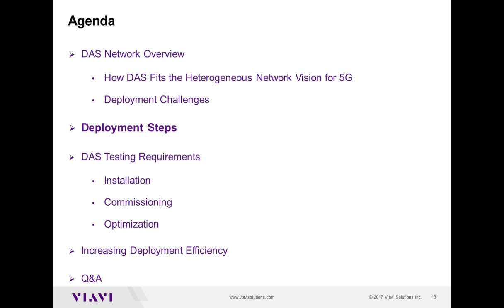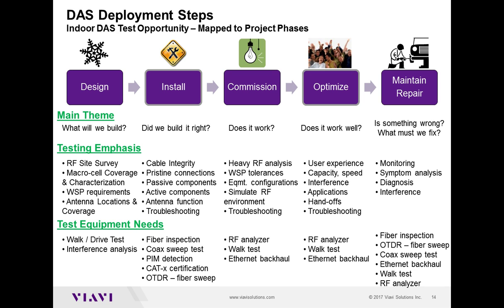So now let's look at the deployment steps. First, I will go through the high-level steps, right? And we'll talk a little bit more on each and every one of them from a design perspective, why we do certain things in deploying the DAS, right? So before even the design, there is one thing that is typically considered as part of the design, I would say, which is usually the benchmarking aspect of it, where you actually take an RF scanner and you do a good baseline to ensure why we are doing what is the intent basically of deploying a DAS at a certain venue.